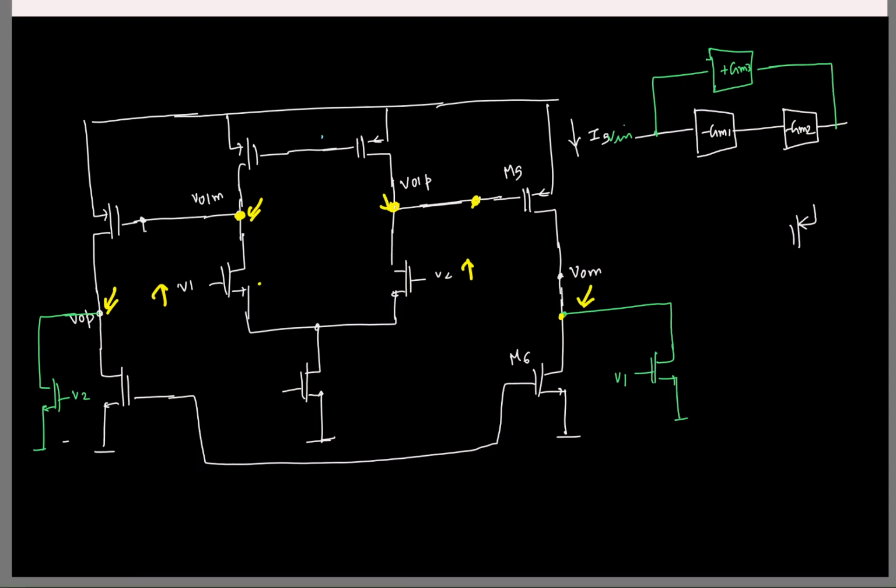In the common mode half circuit, you have this guy, and then the NMOS transistor, and then the bottom current source. Let us say this is an ideal current source for now. If this is an ideal current source, what can you say about this voltage? If I make any change to the voltage here, nothing will change, right? This is the common mode half circuit.